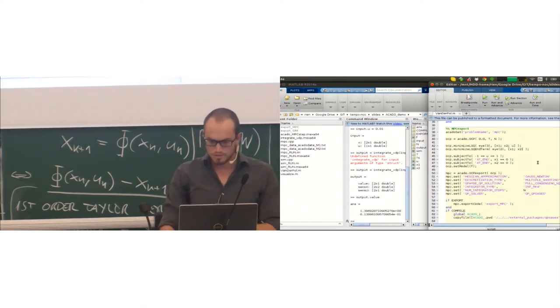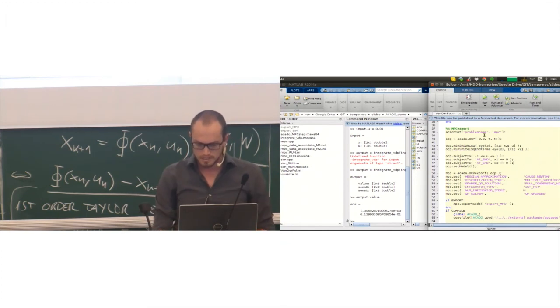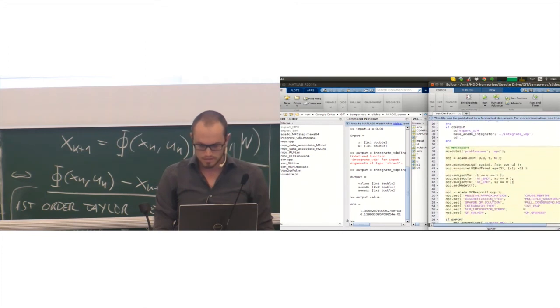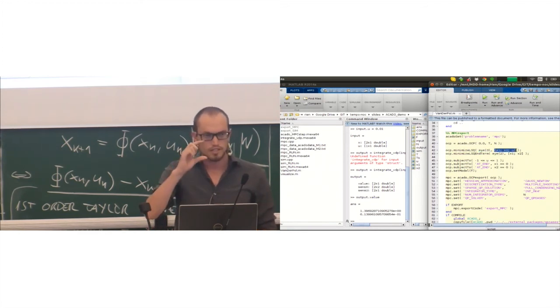Let's formulate the OCP as well. For this, we have to define our horizon, of course. So this big T is, I think, 10 seconds in this case, and I have 20 intervals. And I have to define my objective, which is this least squares cost. It's a simple one. The first argument is the weighting matrix. I just chose identity. And the second argument is a residual. If you remember this function f, which needed to be minimized in the least squares term, that's this one. It's not a nonlinear function. It's just a concatenation of my two states and the control.